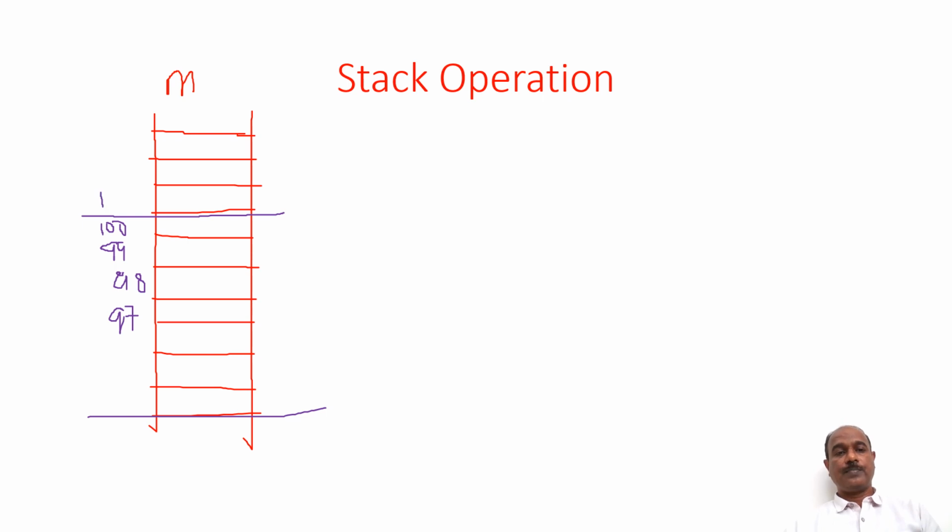Now the address of this location which is above the stack is 101. Assume that it is 102. Now whenever I want to use the stack in MSP430, first I have to initialize my stack pointer. Now this is the part of the memory which I want to use as a stack. So what I should do is initialize my stack pointer 2 locations above the location from where my actual stack starts.